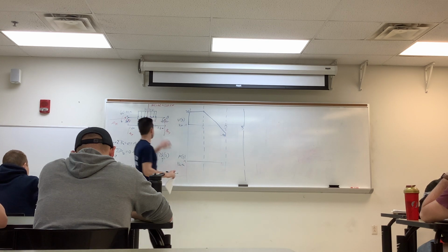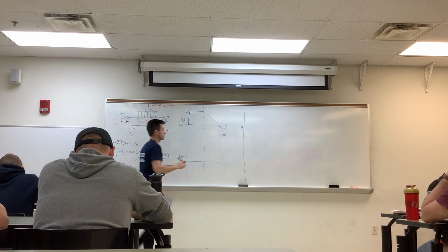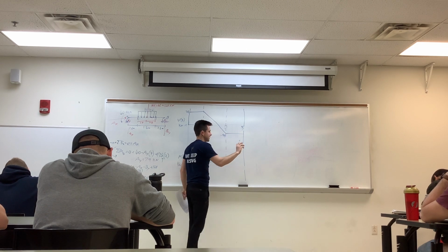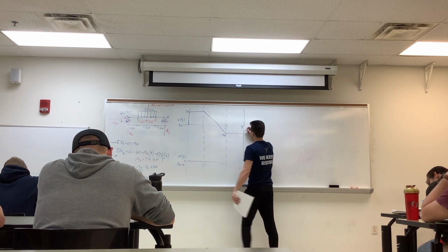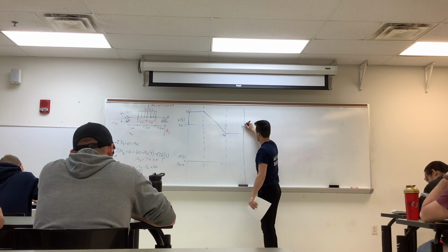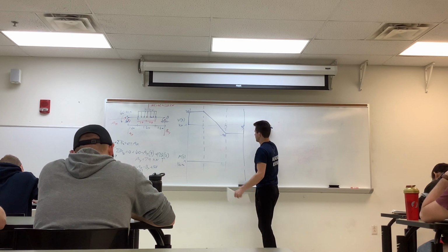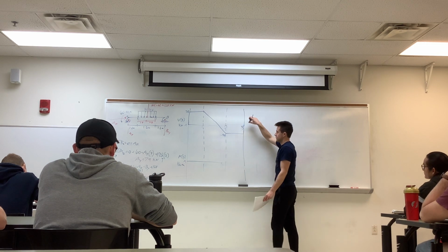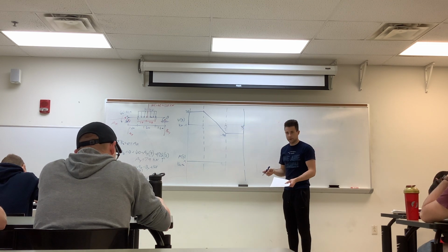There's no change in shear from D to B, so again, just horizontal. And then at point B, there's a positive 49 kilonewton force going upwards, bringing us back to 0, indicating that this shear diagram is correct, because we both start and end at 0 here.